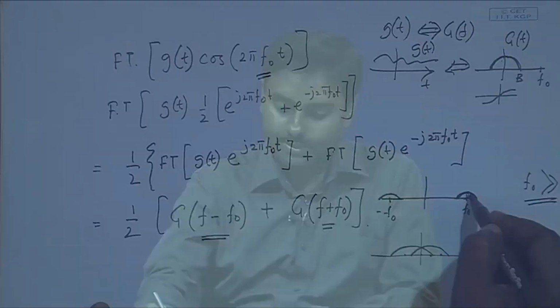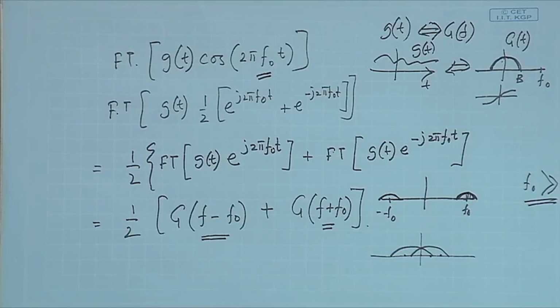The relative strength at every point is relatively equivalent. Okay. So, the signal pattern remains almost the same. What is happening is I am just translating them to a higher frequency. The relative shape remains the same. And this particular part is called modulation.